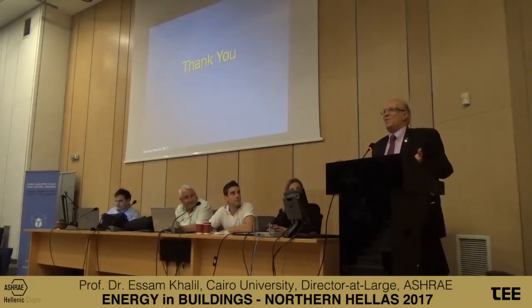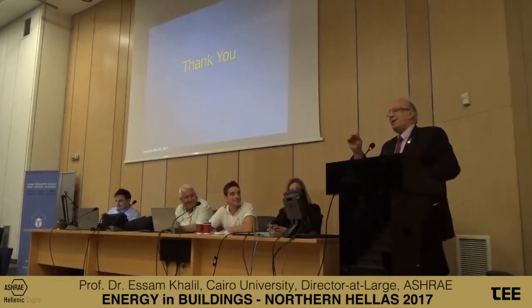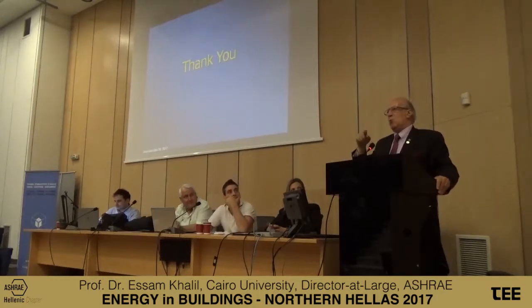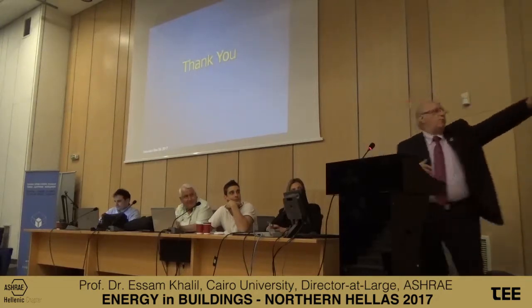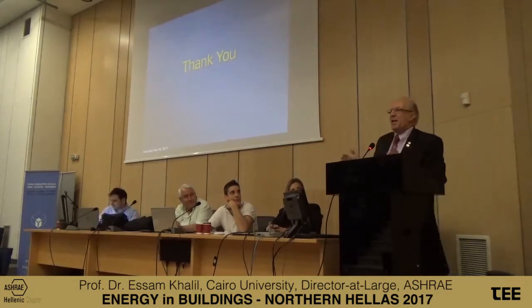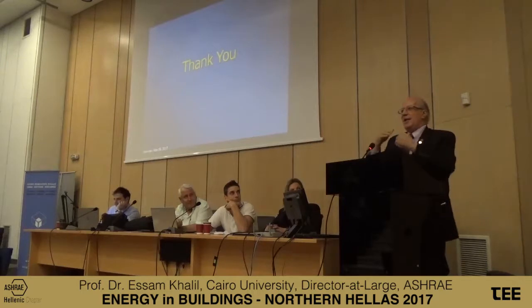So they called us. Of course, nobody believes in university professors. So I went there and we tried to get a solution, and I have 16 tombs to work on. I finished one, which is Hor Moheb. It's called KV57, and it's working. They used to have to put their hands on the wall like this, and water comes. So the solution was to limit the number of visitors and to build a ventilation system, so that you have the fans operating, then the relative humidity goes down, then you allow visitors to go, and so on. And you do this cycle.